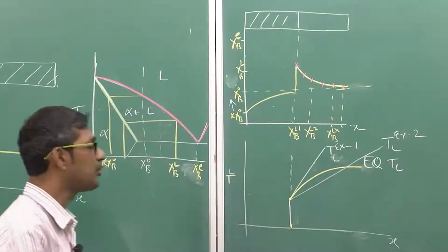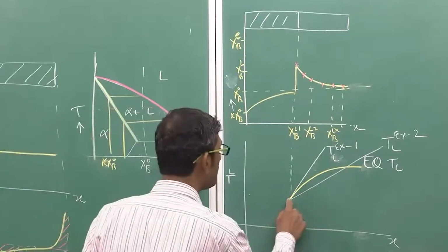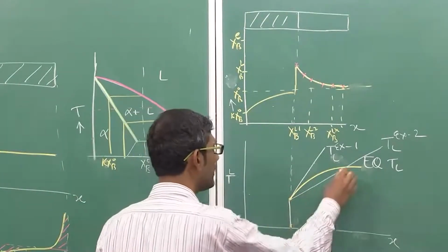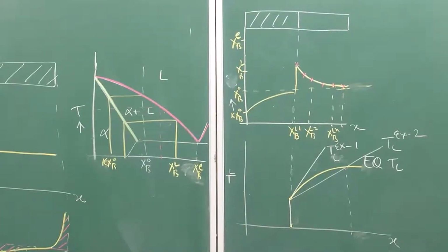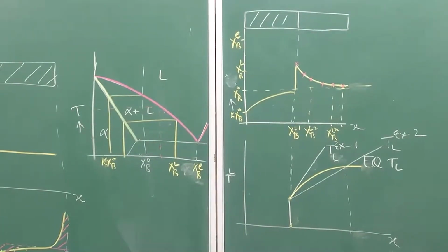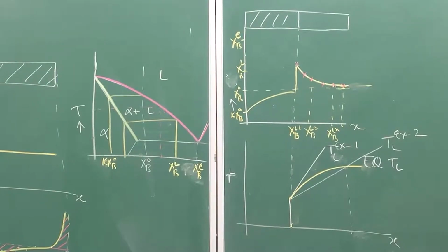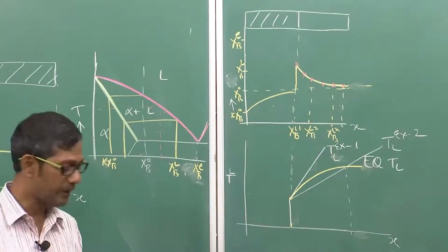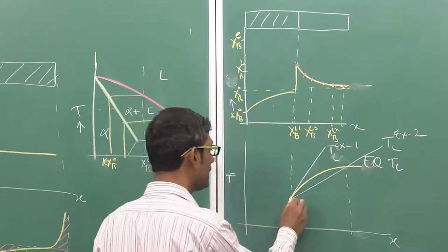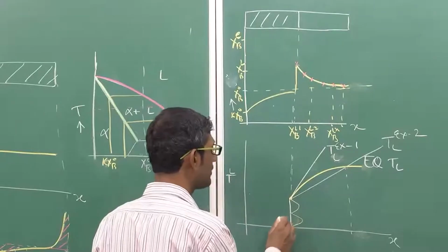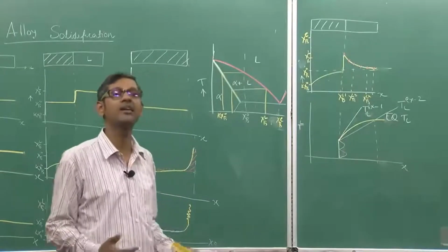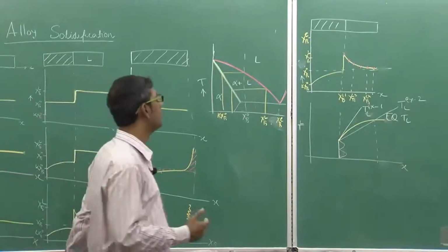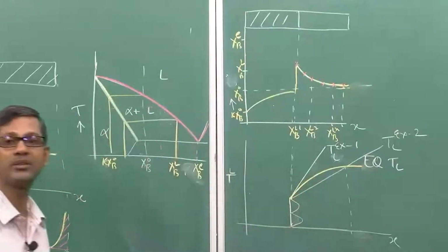As you see, in the region from this part to this point, the actual liquidus temperature of the sample, the experimental TL experiment 2, is lower than the equilibrium liquidus temperature. So, because the temperature is lower, if a solid protrusion forms here, it will feel comfortable and will not melt back. It will be undercooled, because the temperature is lower than the equilibrium liquidus temperature.